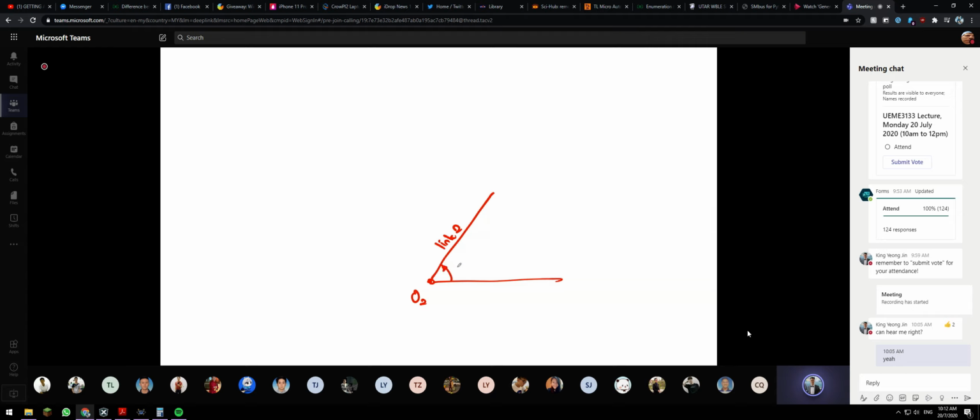So I have 60 degrees here. Where you read the question, it says that theta 2 is 60. There is a theta 2. And then my center of gravity for link 2 is 76.2 millimeters at the angle of 30 degrees from the line center. That's why you have to draw another line, because this is the line center.